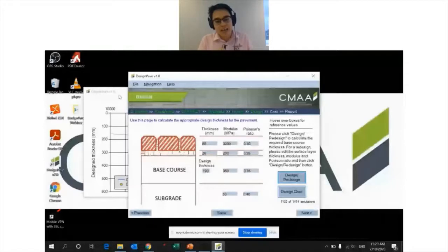Okay, and it's doing that in 5mm increments. So if you had the ESA, you could pinpoint where on the graph your pavement will fail, or if you need to extrapolate it, you can create a thicker base to accommodate 100,000 ESAs. So right now it's just loading all the data.